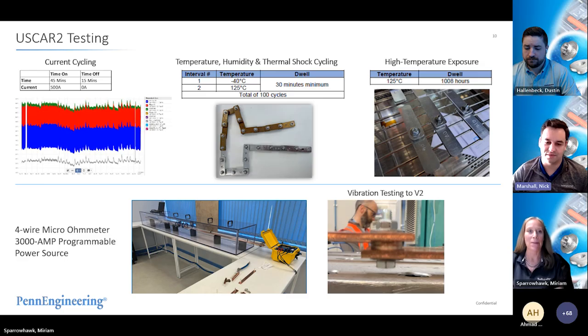After 24 hours of continuous vibration, the joint with the bolt, the nut, and the 2 bushings performed exactly the same before and after. And during continuous continuity monitoring, we saw no issues. But actually, the bus bars themselves, where they're joined to the testing rig, would fail in fatigue. So it speaks to how important the design of the whole system is in ensuring that the electrical joint will be consistent. But it also speaks to how, when we're looking at the reliability of our parts, we're really focusing on not being the weakest link in the system. We want to outperform the other components that we're connecting with.